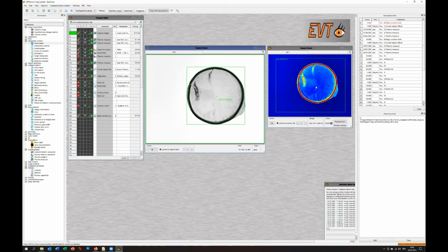Normally there's a print on top and you simply see the top foil, but the interesting thing is, because the heat is not working around, you see here the broken gap, and that means the seal doesn't work. Whatever is printed on top, you see it because of the heat of the camera you have used. It's a thermal camera.